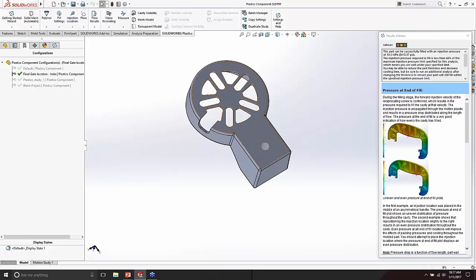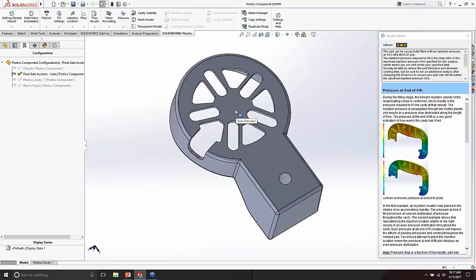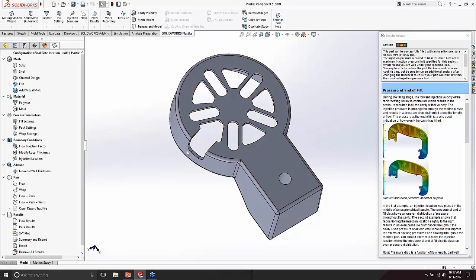What I'm going to decide to do is actually do a post-process. So I'll fill this model up, and I can use this volume, this location here, and use a post-process to actually drill out that hole so it gets a nice and clean hole, but it gives me a little bit more surface area to work with, trying to eliminate some of those weld lines so we don't get as much cracking. But then we might introduce other issues, right? We might introduce cracking due to the drilling process at the end of it.